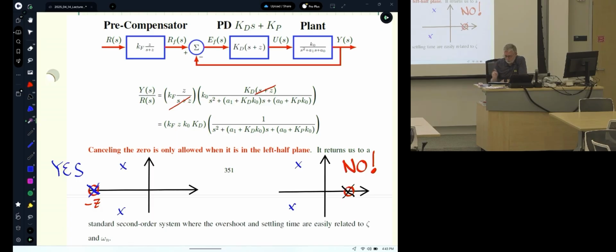And here, the precompensator is set up so it's got z over z, so when you set s equals 1, the gain just becomes z over z, which is 1. So this coefficient kf is the gain of the transfer function, and we'll use it in just a second.